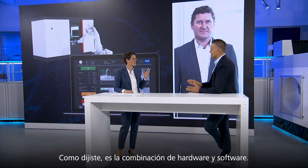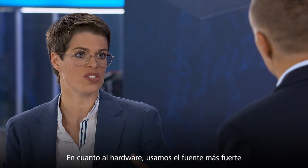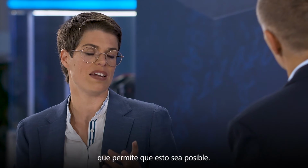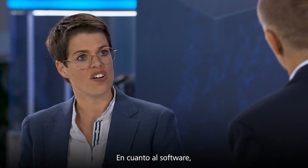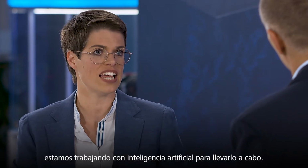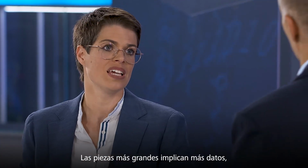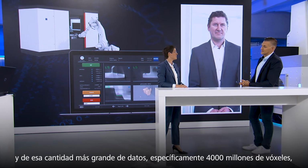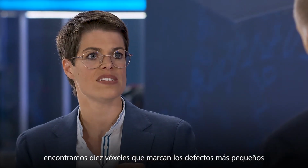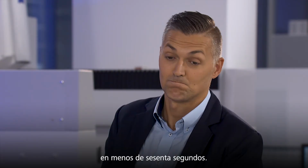Well, as you said, it's the combination of hardware and software. On the hardware side, we used a brighter source, and our Zeiss expert invented a new detector concept that makes that possible. On the software side, classical concepts won't do it. We are working with artificial intelligence to make that happen. Because of the bigger parts, we have more data. And out of that more data, namely 4 billion voxels, we find these 10 voxels that mark the smallest defect within that less than 60 seconds.